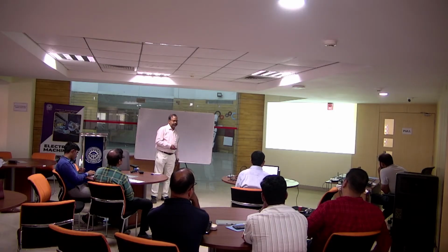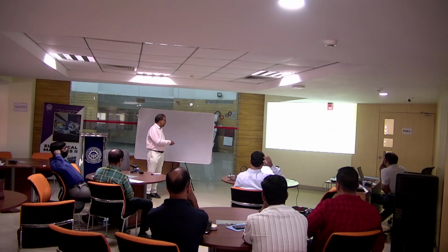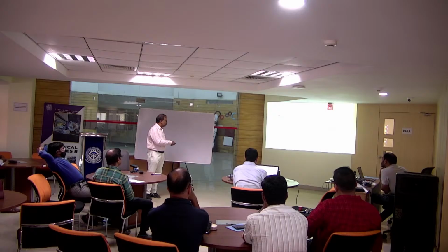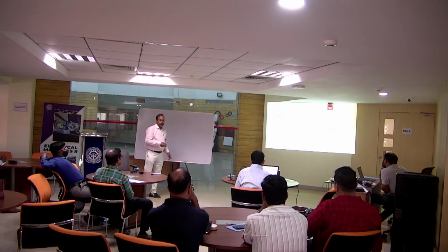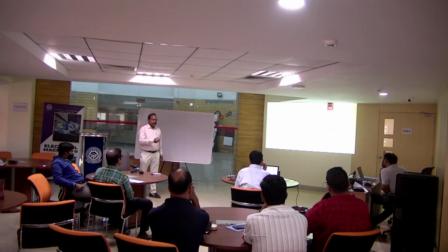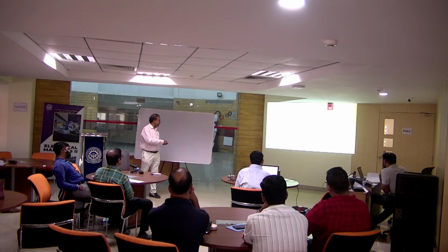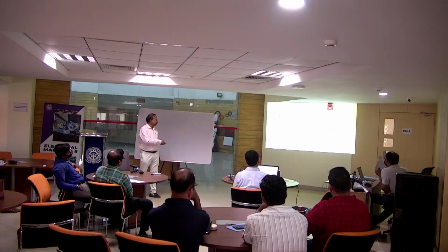Plugging I have already explained. You know the slip equation. Slip is given by s equal to synchronous speed minus motor speed, divided by synchronous speed. When you change the phase sequence by interchanging two terminals, the magnetic field rotates in the opposite direction. So instead of plus omega s, you write minus omega s because it is rotating in the opposite direction. So now slip is 2 minus s, more than 1.